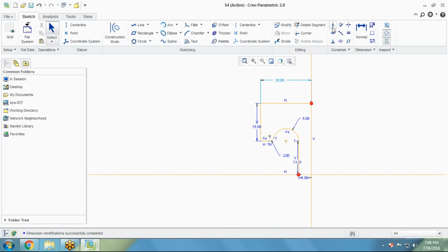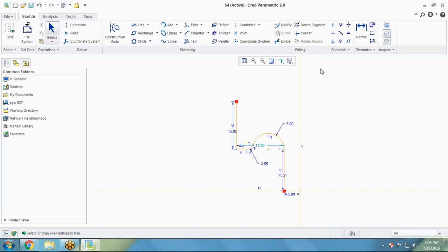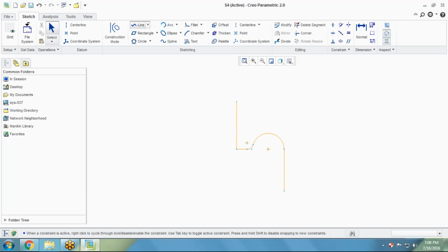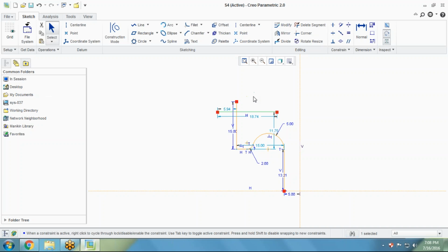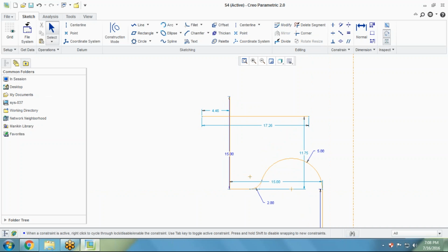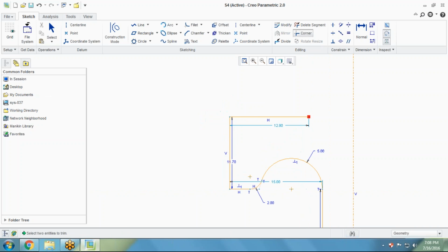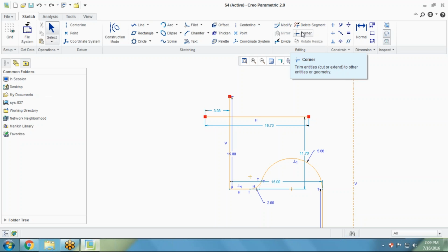After that we can do one thing, we have one more option there, which is delete segment. I have already worked on this, means select on this line, so the line will be deleted, right? So the next operation is corner. So if we have just used these two lines, now we'll see there is some corner, so I'm just deleting the corner 1, 2, the other one will be deleted simply. If I'm using the fillet, the radius is coming. If I'm using this, the radius will not be coming.